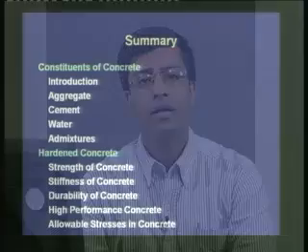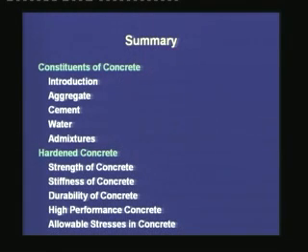It specifies a minimum cement content and a maximum water to cement ratio depending on the exposure condition. The exposure conditions are defined as moderate, severe, extreme, and so on. Now, those definitions we are not covering here because those are already covered in IS 456, and then we studied the definition and the types of high performance concrete.